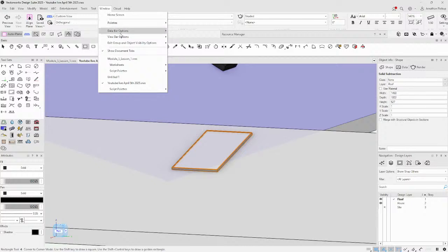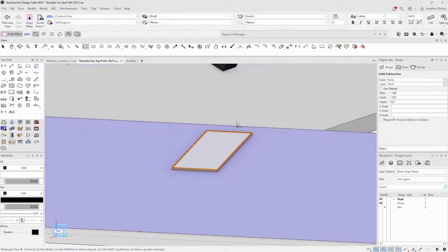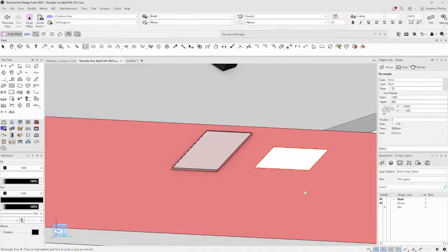So I'm going to change that so that whenever I start to create an object, I don't have to hit the tab key to get started. I can just type in the size I want. Tab, -800, enter, enter. And to me, that's a really quick way to model.